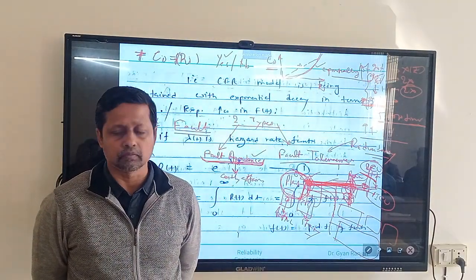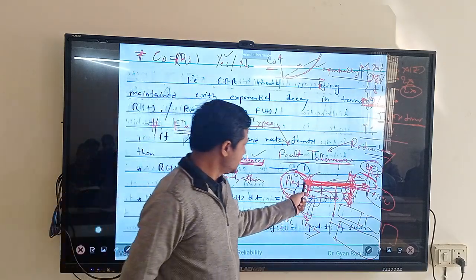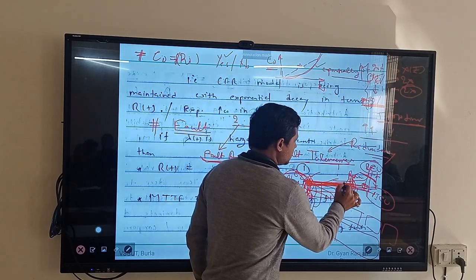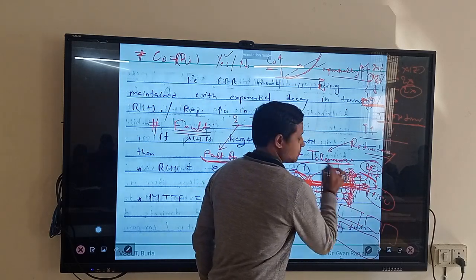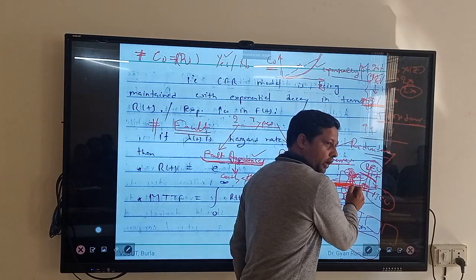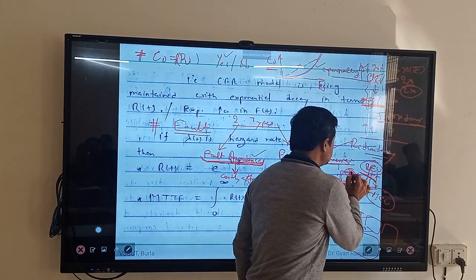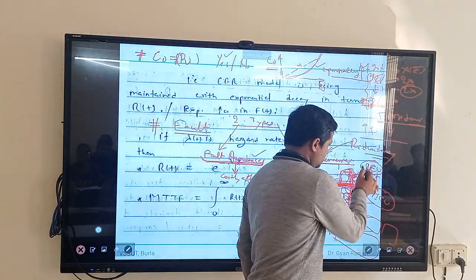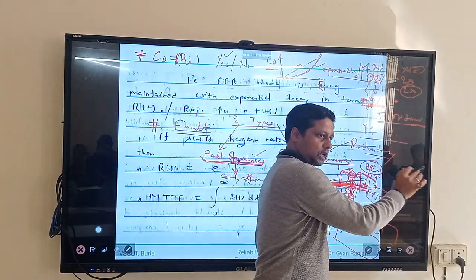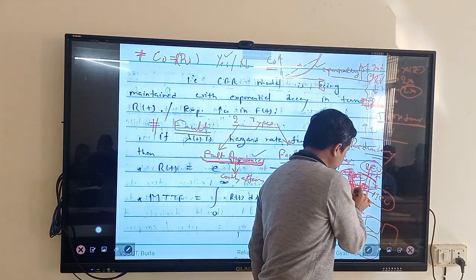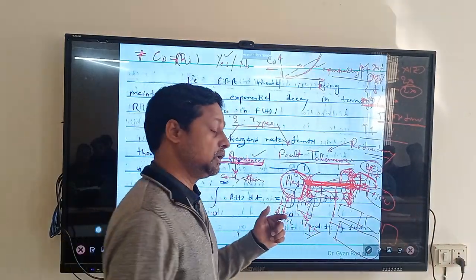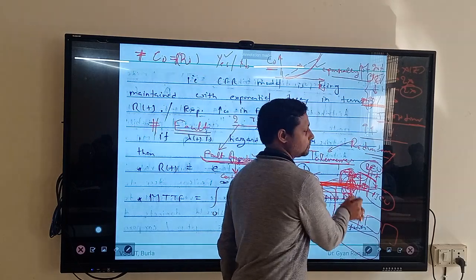This will remain one common line, but I will add one redundancy here and one redundancy here. So if one valve fails, it will automatically reroute like this. Now service is not interrupted. The engineer will get time to properly maintain this line, and once it is maintained, it becomes active again. The work continues. So better than adopting the previous method, you do this.